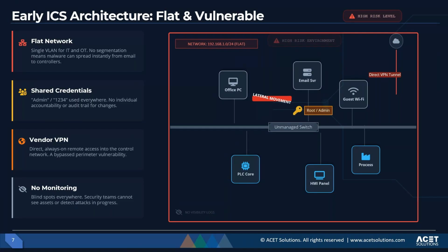The use of shared credentials across multiple systems was a common practice, which eliminated individual accountability. There was no way to trace who made configuration changes, executed commands, or accessed a critical device. On the other hand, these environments relied heavily on open industry protocols, such as Modbus, DNP3, and Profinet, that were never designed with security in mind.